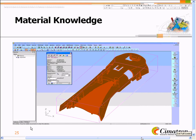For instance, here you're looking at how the software interacts with the data received so that I understand the part. I'm quickly getting the overall volume. I'm looking down and finding resistance to clamp. All that information I'm going to need to know when I start laying out the overall steel sizes for this part. This is also a situation where I would put in the shrinkage so that that information stays with the job throughout the length of the job.